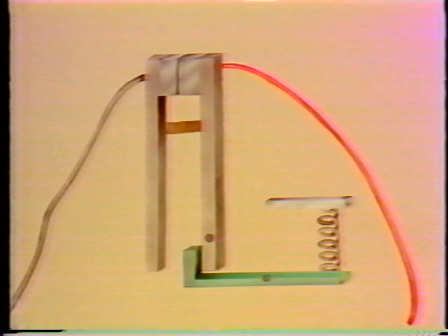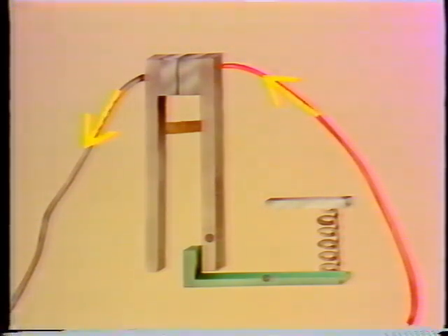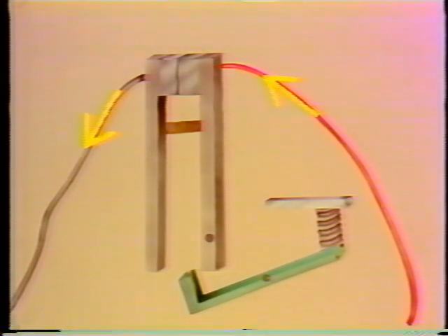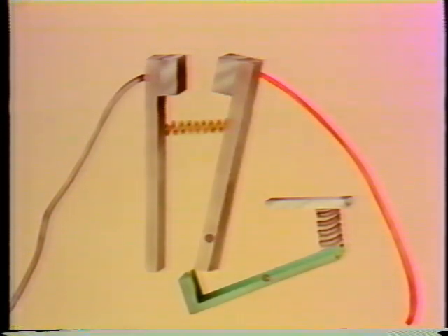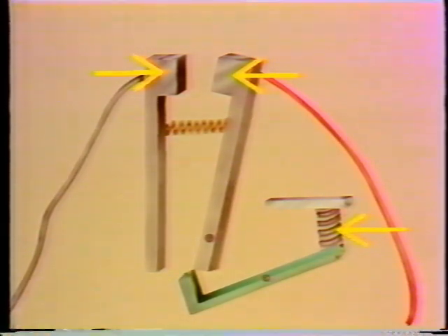When the circuit breaker is closed, current can flow through it. This circuit breaker will open whenever something happens to overcome the tension of this latch spring and move the latch like this. With the latch out of the way, the contact spring pushes the contacts apart, opening the breaker. The breaker stays open until something happens to close the contacts. We'll see how this is done in a little while. In most breakers, the latch spring just returns the latch to its normal position. It doesn't close the contacts. To make it easier for you to see how the contacts operate, we won't show the latch spring anymore. Just remember that as long as the contacts are open, current can't flow through the breaker.